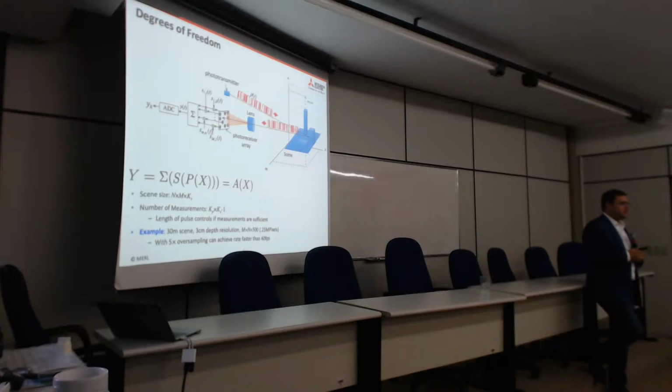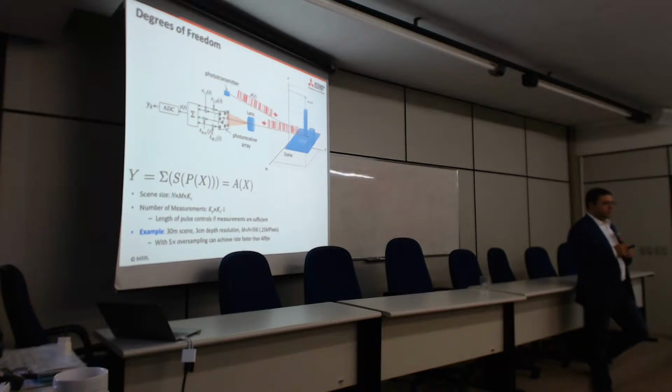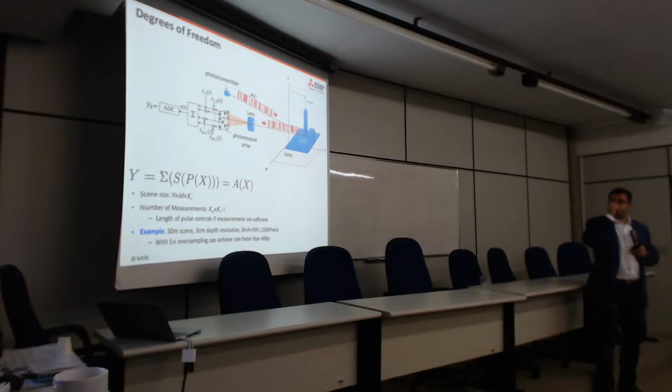That's easy. Many people use photodiodes like that for optical communications that go 60, 100 gigahertz, and so on. Okay, gigabits. The next part is those multipliers. There are very good multipliers that can do this process, and you don't need an actual multiplier with any arbitrary wave. You need a 0-1 multiplier or 1-1, and that is a switch. You just do it with a switch. Again, this has been done in communications at those rates, like 60 gigahertz or so on. So you're very well off there.